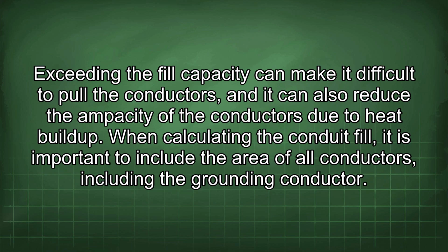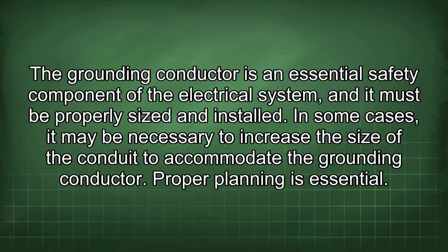When calculating the conduit fill, it is important to include the area of all conductors, including the grounding conductor. The grounding conductor is an essential safety component of the electrical system, and it must be properly sized and installed. In some cases, it may be necessary to increase the size of the conduit to accommodate the grounding conductor.